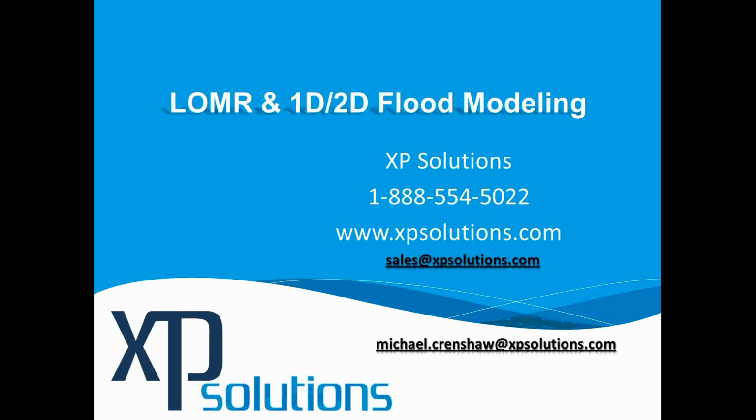Please clarify when the duplicate or corrected 2D model should be introduced. The 2D model could be introduced, I think, at the corrected effective model point. If it's man-made changes, I would hold off until you get to existing conditions, but I think at either one of those points you could introduce the 2D model. And can you use multiple grids with different cell sizes in one model? Yes, we can. We have finer in the channel or in an urban area and a more coarser grid out in a rural area, etc.